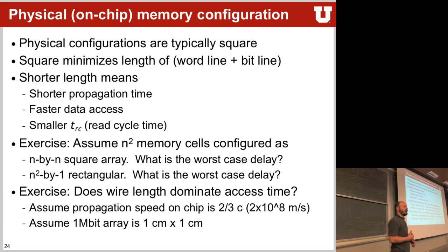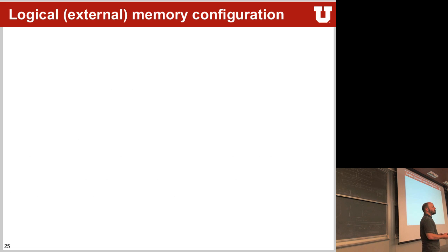So know that the propagation delay itself doesn't have much to do with the area or the behavior of it. It's more about the surrounding logic and the particular technology that you have in your memory cells that will determine the access time and the speed at which you can actually read that memory chip out.